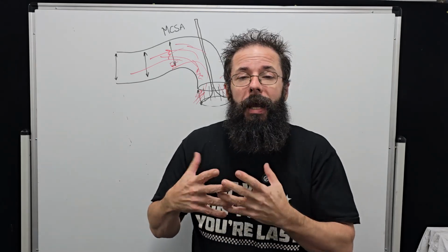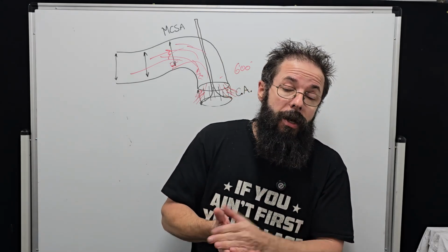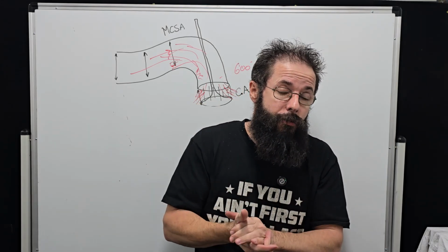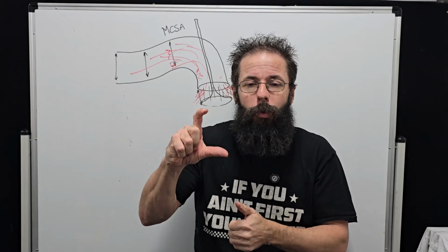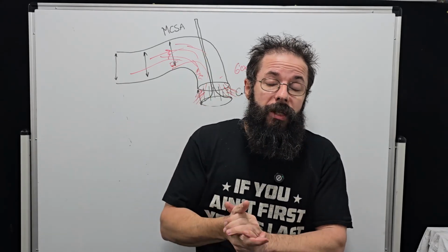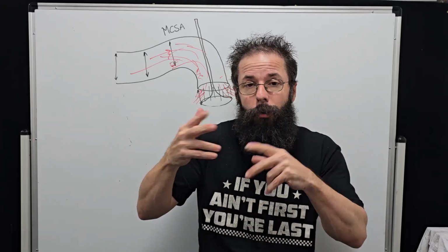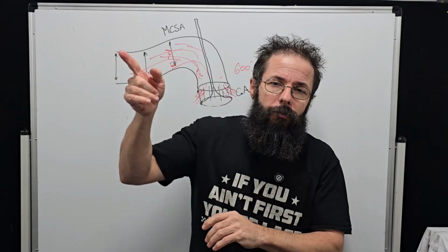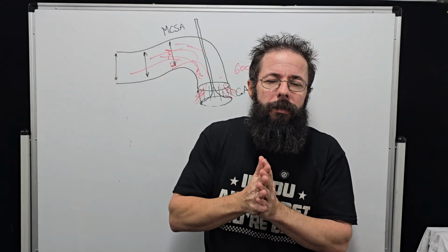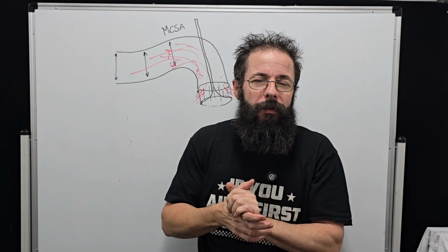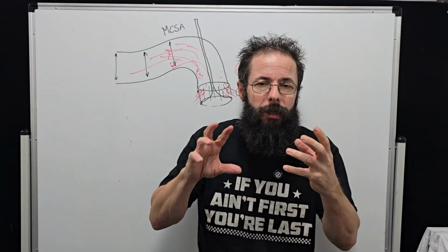And even some port entries, we've seen this in the 4G63 in the non-turbo, massive windows that choke down really quick. The European CA18s, I actually do a full weld up on one of those. I might show some pictures. We did a race car in Sweden. Yeah, we basically changed the whole shape. I might even pull the port molds out if I've got them, because that's something I get into as well.